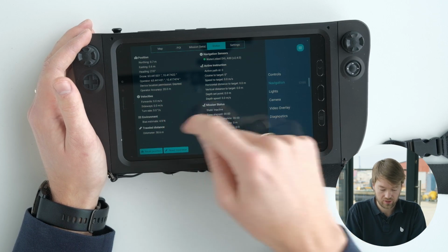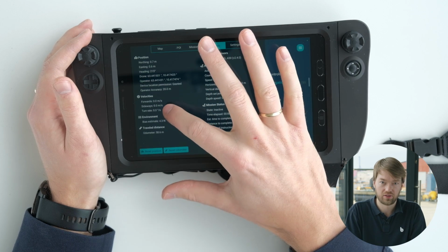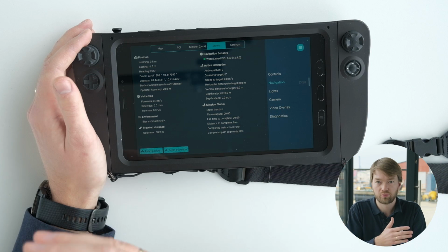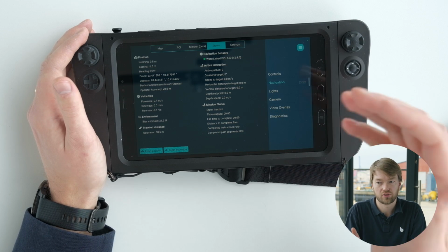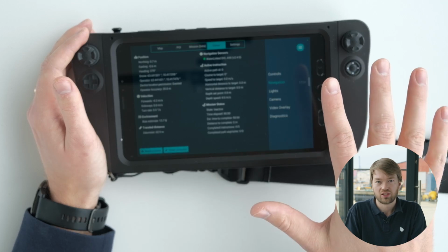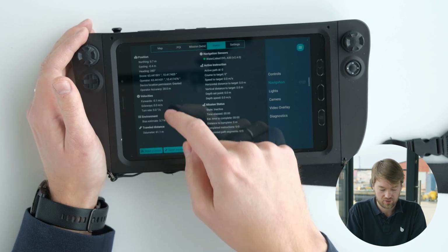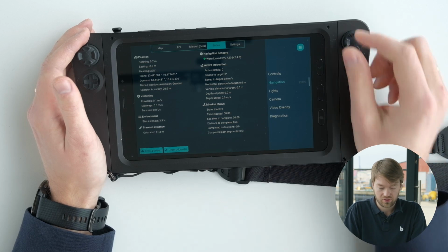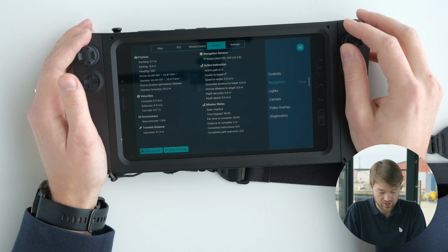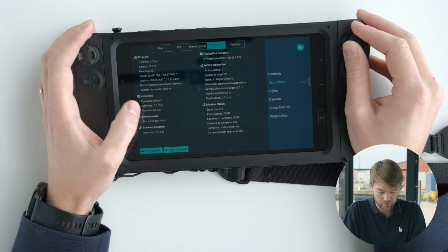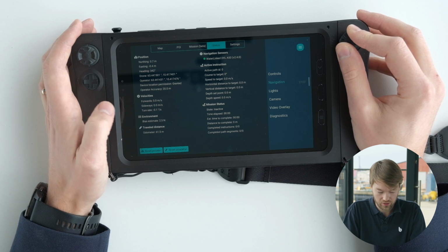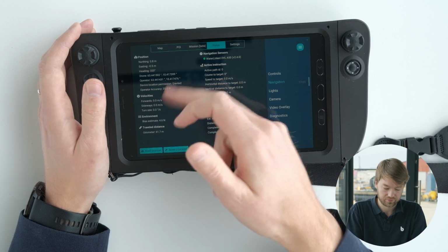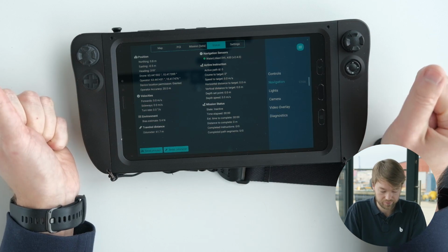Below that you can read the velocities reported from the DVL. So this can be used if maybe you want to measure the water flow in the river, then you can just disable station keeping and let it flow down, and then you can read here the velocity. Or you could see how fast you're driving forwards, for instance. You can also see the turn rate if you're turning, and yeah, basically a nice speedometer to have.